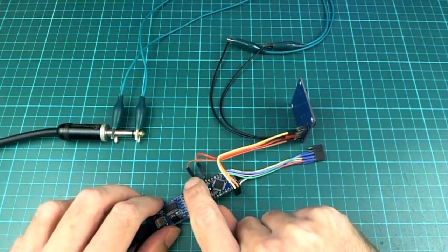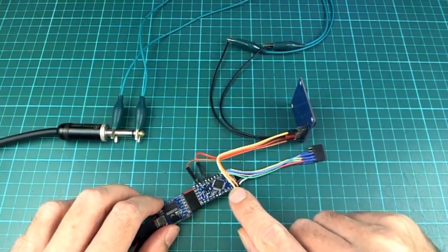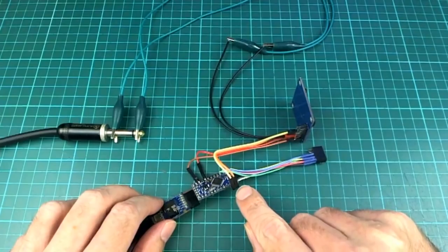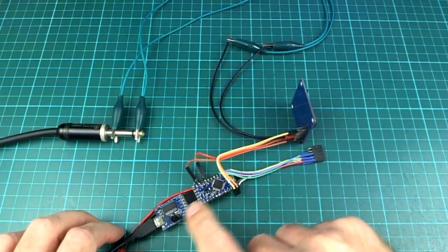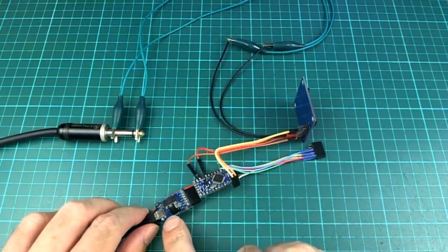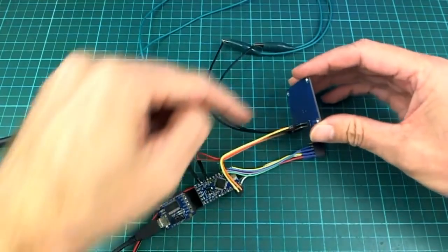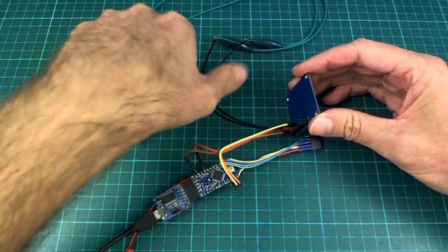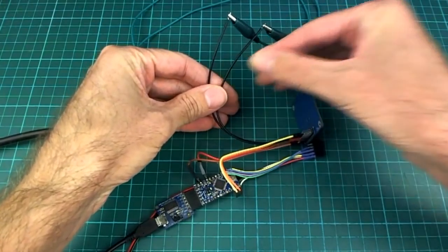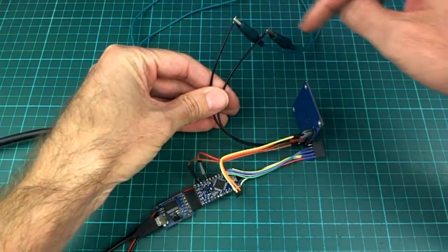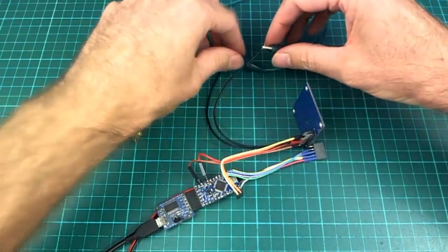So all I have to connect here is ground, 3.3 volts, and then RX and TX for my UART, and I've put those on pins 7 and 8, so this is going to be a software serial, and this is just running into my computer, and on here I have 3.3 volt selection. The only other connections are these two wires here, which is for the audio output. These don't have any polarity, obviously. They're just creating waves of sound.